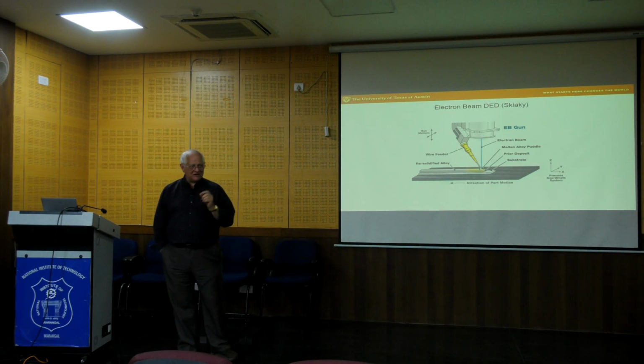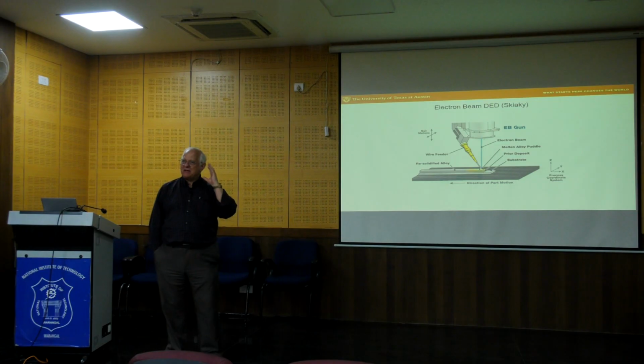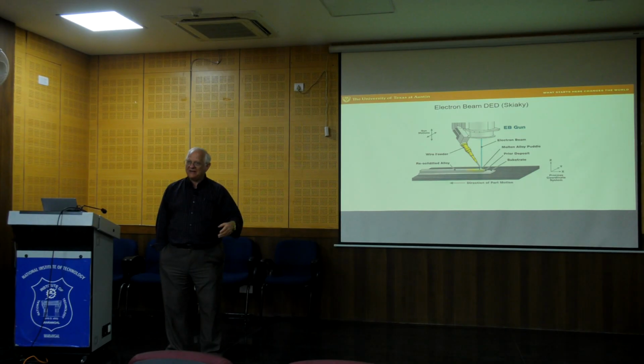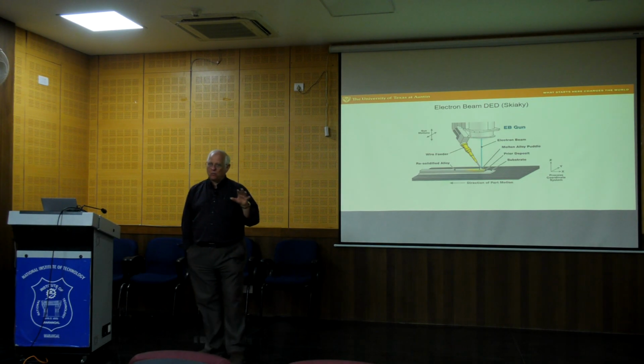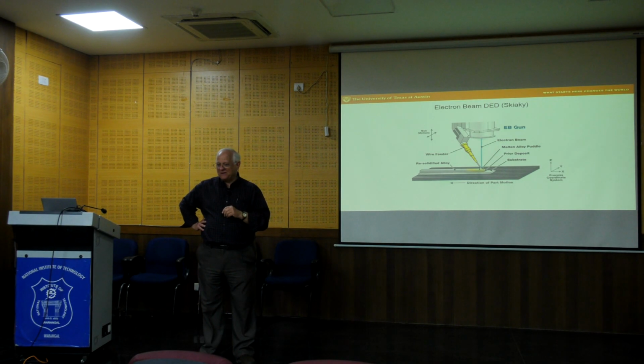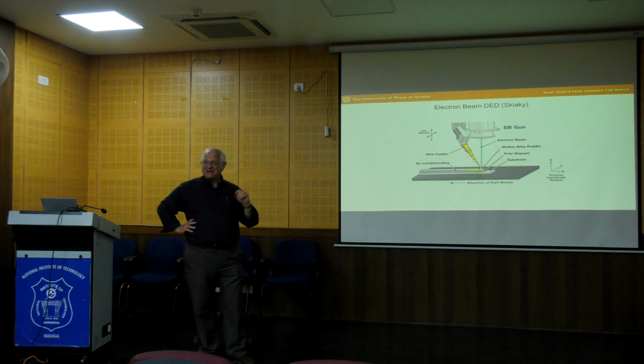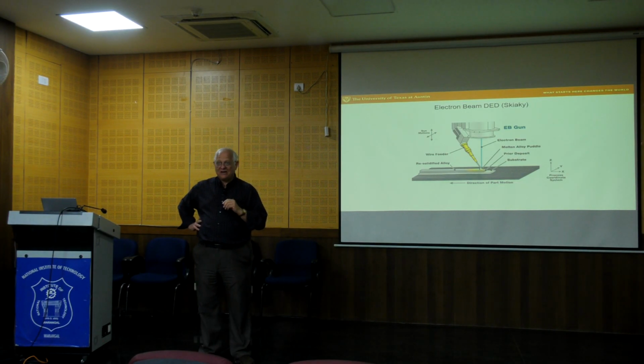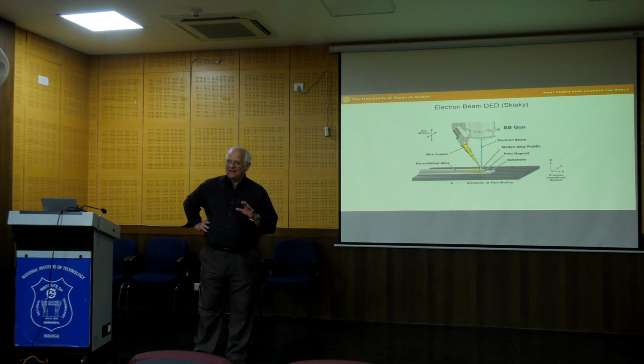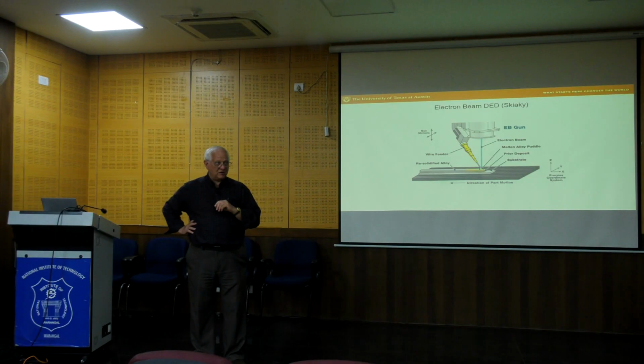I would mention as an aside that it doesn't make intuitive sense, but it turns out that if we look at issues like the environment and energy uses and sustainability, in terms of manufacturing, what's really the most environmentally friendly, what makes the best use of the energy, it turns out that actually this technique is the best among the additive processes. There's a plot that was created by an MIT professor whose name was Gutowski. So we call these the Gutowski plot.